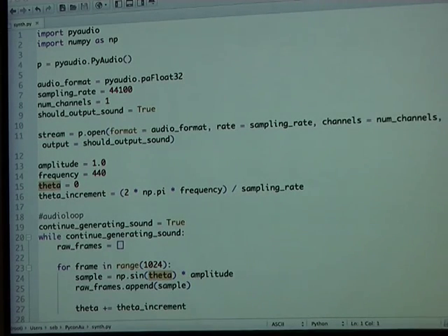So we could, if we wanted to be a bit more clever, pre-calculate, because we know that sine's never going to change. We could pre-calculate all our samples and just store them in a lookup table, and instead of actually computing the value of sine again every single time we need a new sample, we could be much more efficient and just look it up from a table. But we're lazy today, so we're not going to do that.